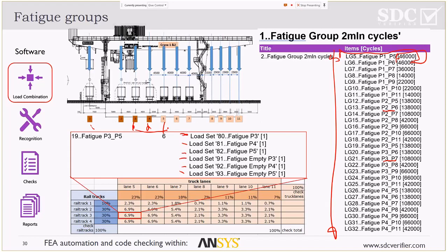We recognize the weld, so we know the total section height, and we can calculate for the different situations. You could already calculate the critical length based on formulas. I have a student who already did that, but implementing the full BS or DNV will take somewhat longer, but that is definitely a very high priority. It's not going to be the first step, but probably the second. So I hope to have that next year in December included.